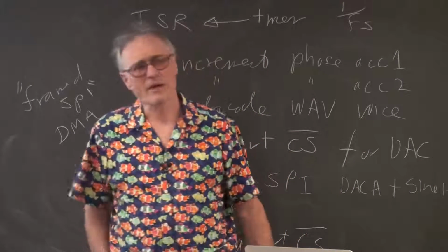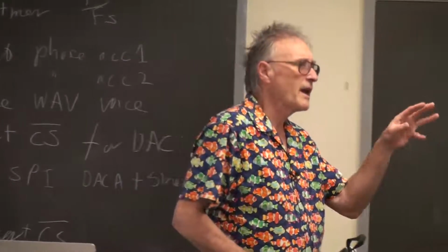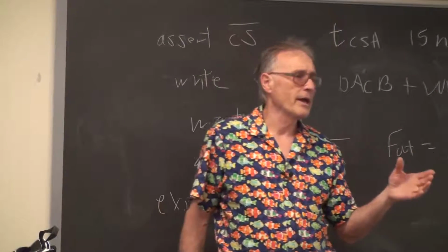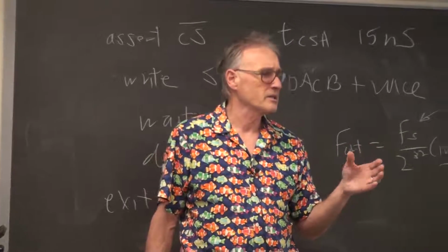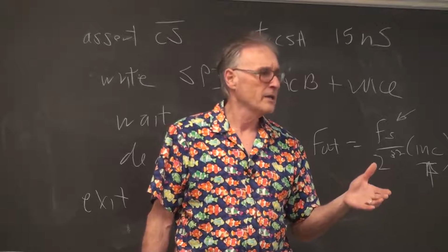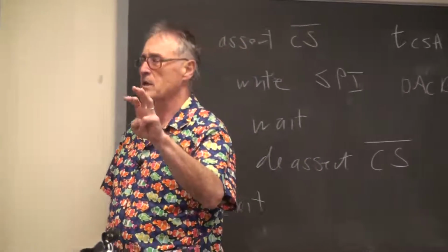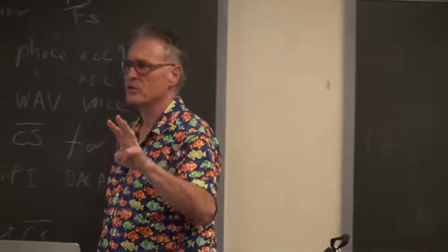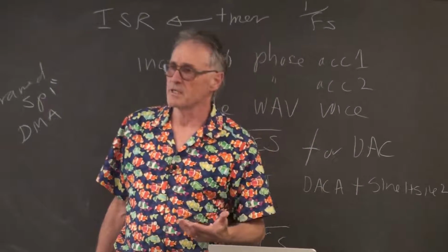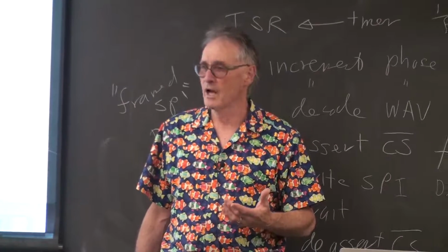The bandwidth of speech is only about 3 kilohertz. There are a few very high-pitched sounds that help discriminate the speaker and particularly consonants. Almost all of the energy for vowels, o, e, a, e, is in 3 frequency bands, and the highest frequency band is around 1.8 or 2 kilohertz or so. Most of the high frequency energy is in the consonants. S, ha, p. Those are all high frequency sounds, right?